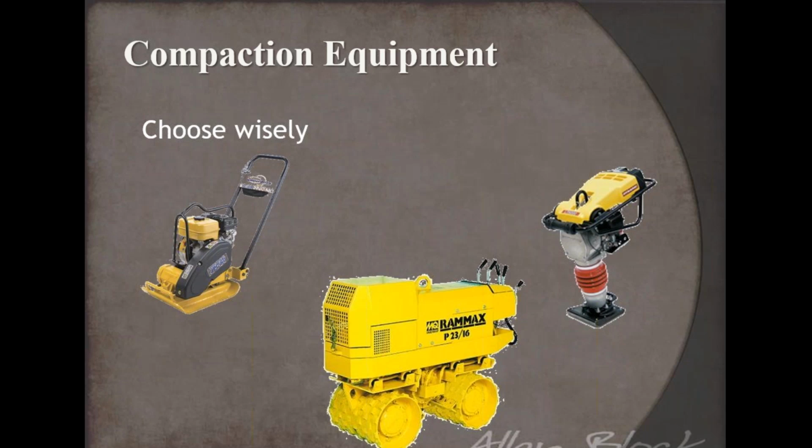We love it in and around the wall, the block itself. So on top of the block, behind the block, it helps consolidate the rock that's in and around that zone. But when you're talking about fine grained material like your clays and silts, that's where those rollers really come into play. You might have to put a little vibration to it, but when you're talking about clays, we actually like to kind of roll it through and kind of knead it together, so you're removing some of those air pockets in there too.